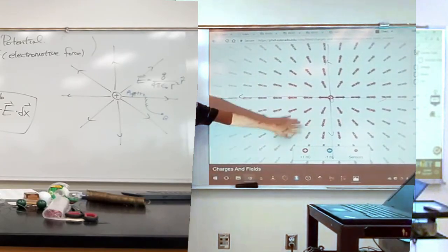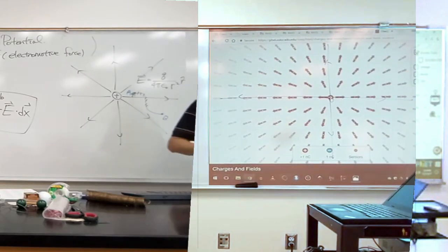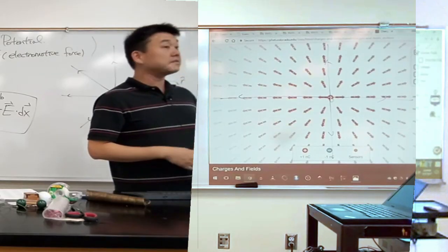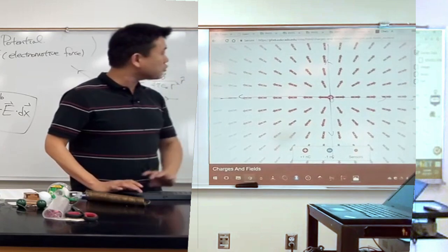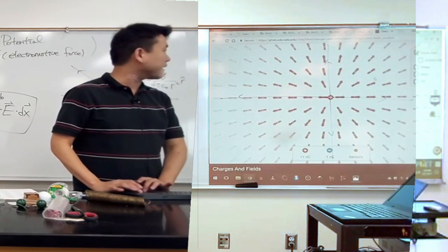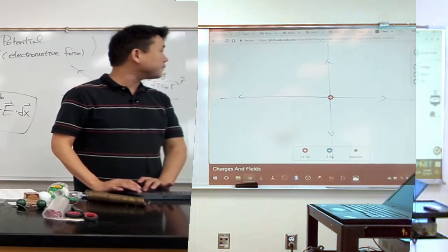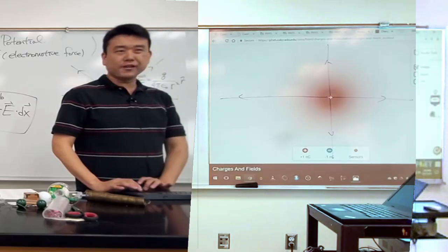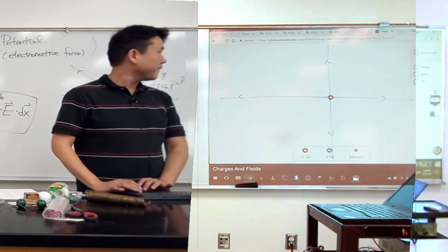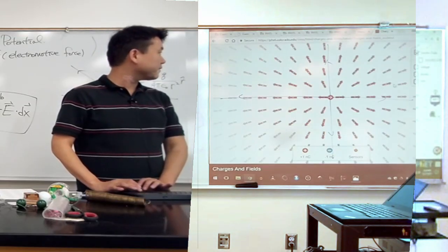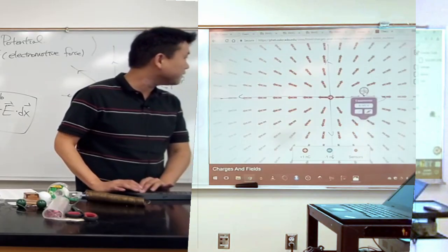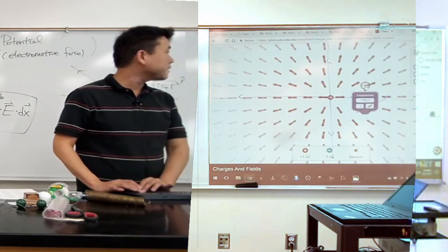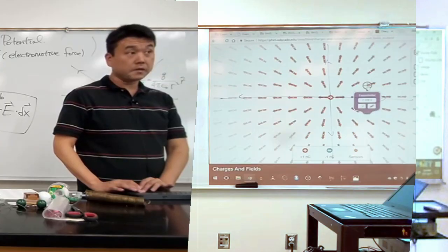Now, what you can do with this tool is draw a set of lines that helps you visualize the voltage. Unfortunately, if you simply go to voltage, that doesn't really do it, because it's doing a gradient thing. The tool that you need to use is actually this tool here. This is the tool that's going to draw equipotential.